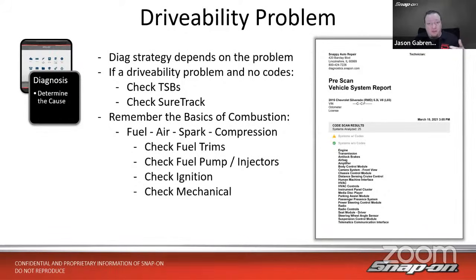What kind of injectors do I have? Are they top feed? Are they side feed? Are they direct injected? What am I dealing with here? What kind of ignition system is it? The waste spark system? Does it have the coil built into the igniter? All of these things, mechanical. What's my compression spec? I have to look all that up.